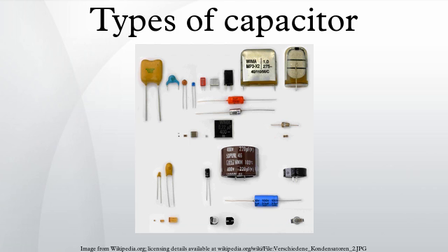Double-layer capacitance. Storage is achieved by separation of charge in a Helmholtz double layer at the interface between the surface of a conductor and an electrolytic solution. The distance of separation of charge in a double layer is on the order of a few angstroms. This storage is electrostatic in origin.